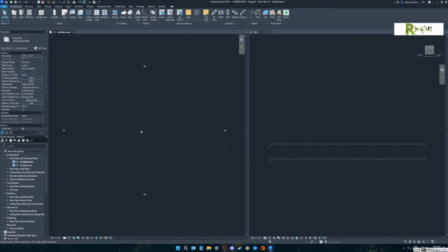Remember that all of this stuff is being drawn in any model views when we draw any of the objects off this architecture tab. Walls, doors, windows, all the things that you were looking at, those are all model objects, including the line. Do you see where there's one for drawing a line up at the top on your icons? See, Model Line, right? Now that's going to be very different than an annotation line.